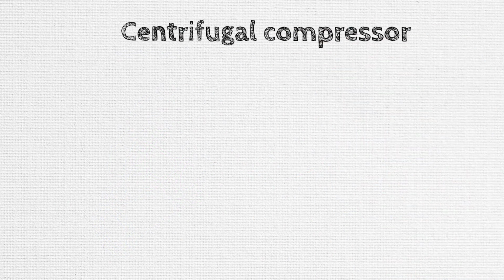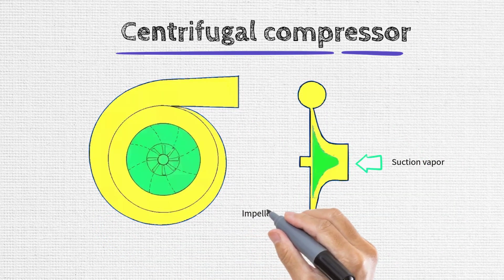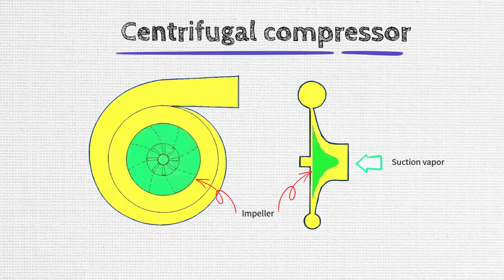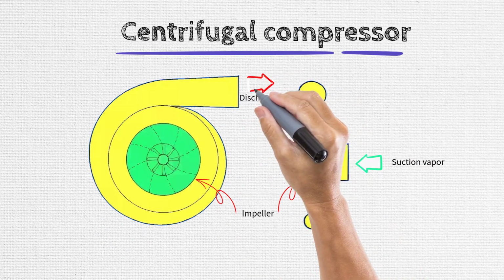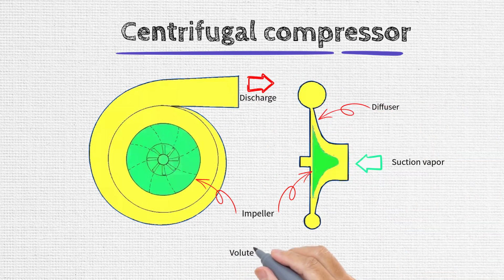In this type of compressor, the vapor is fed into a casing near the center of the compressor. The impeller is a disc with radial blades that spins rapidly in this casing. The vapor is flung outward in the casing, piling on top of the vapor ahead of it, causing slight compression. These compressors are designed to operate at high speeds. The pressure gained is small, so multiple impellers may be used in series. This creates greater pressure difference and pumps a sufficient volume of vapor.